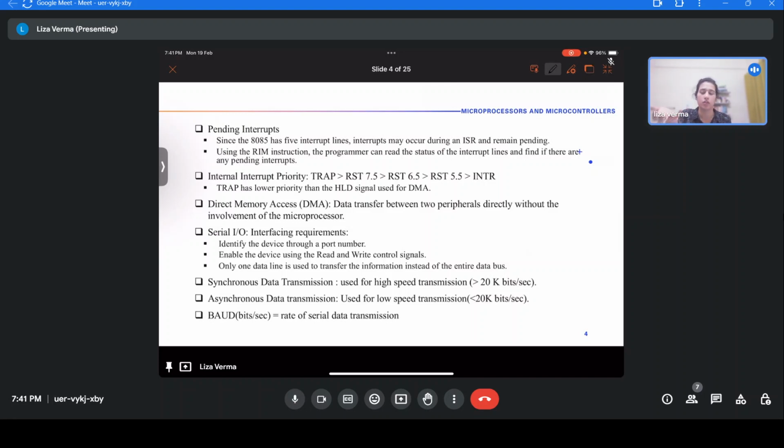If you have worked with it, you'll know what I'm talking about. If the baud rate set at the transmission end is different from the baud rate set at the receiver's end, you don't get data at all, or you get some rubbish question marks or NaN values or whatever, right? That is why baud rate is important.